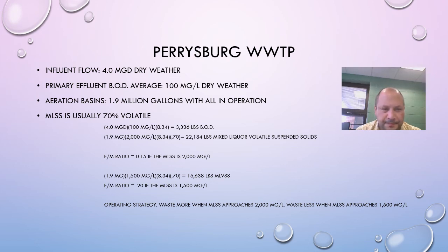And the reason that we did this is my predecessor here at the plant, the guy that left when I moved up to be the plant manager, when he started here, he just told us, hey, I want the aeration tanks at 2,500 milligrams per liter. And we kind of knew from experience that that number was too high, that we were going to have too many microorganisms and not enough BOD coming into the plant, that would create operational problems for us.